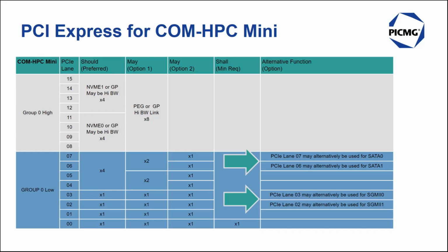On the module, the chipset has only been initialized differently via software adaptation, and the module can, for example, provide SATA on PCI Express lanes 7 and 6. Unfortunately, the required coupling capacitors differ between SATA, SGMII and PCI Express. If the TX coupling capacitors were on the module, the module manufacturers would have to adjust the hardware depending on the customer's application or choose a compromise.